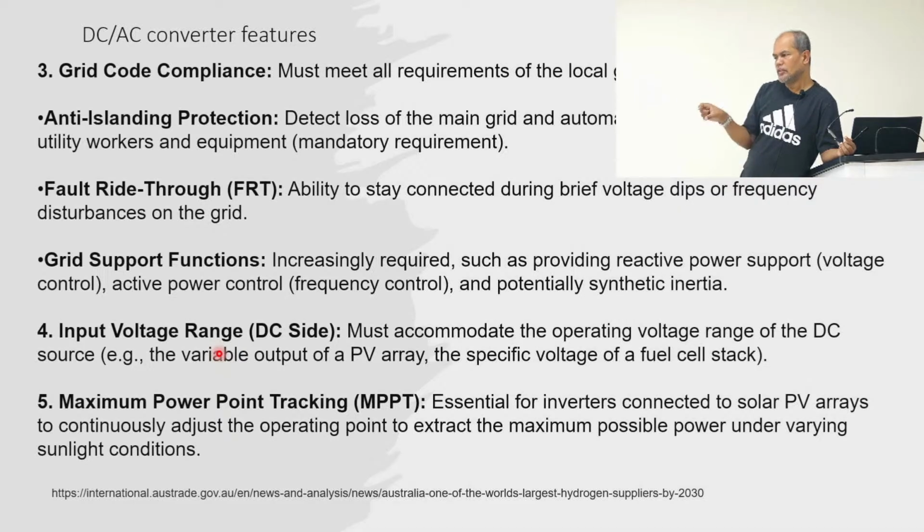So the device should sense that the grid is disconnected, and based on that the protection system can activate, either to shut down or work in another mode. But it has to have that capability for islanding detection and protection.